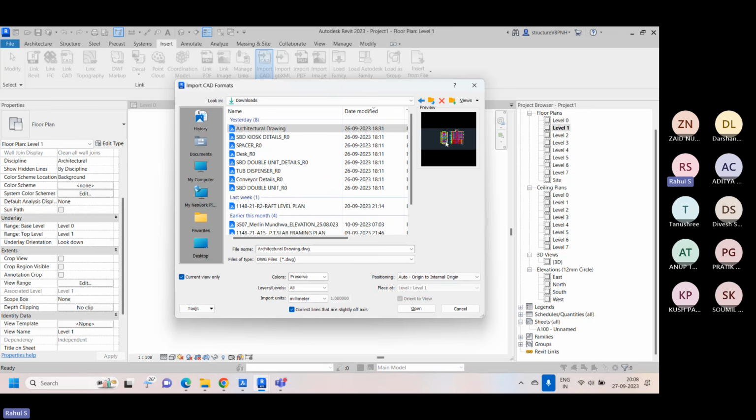When you are combining the models, they will get merged or will not match exactly at one position. For this not to happen, all models and all data must be at one place, which will be aligned to all other services. Then you need a positioning. In industry, people always use shared coordinates for this positioning.